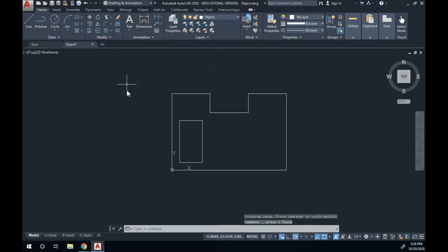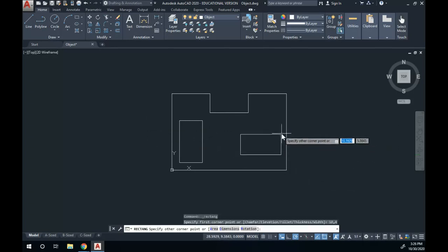Sometimes you make mistakes. So let's do the rectangle command. Specify first point is 18, tab, 4, enter. And then as far as my next point, specify the corner here. Okay, I see what's happening. This is when I misjudged myself. Once you create your first point, it says specify the other corner. The other corner is with respect to the point you just created, not with respect to the origin. So that's why that mistake happened.